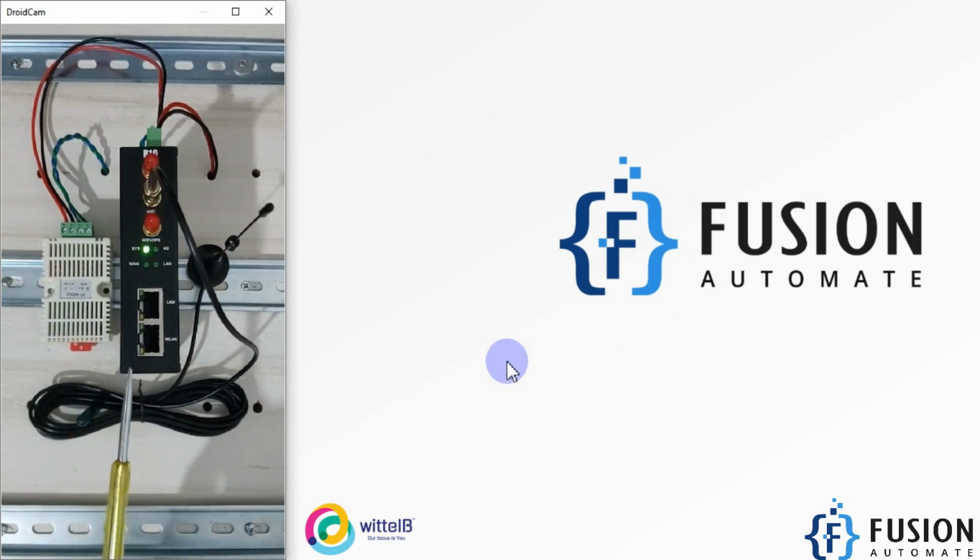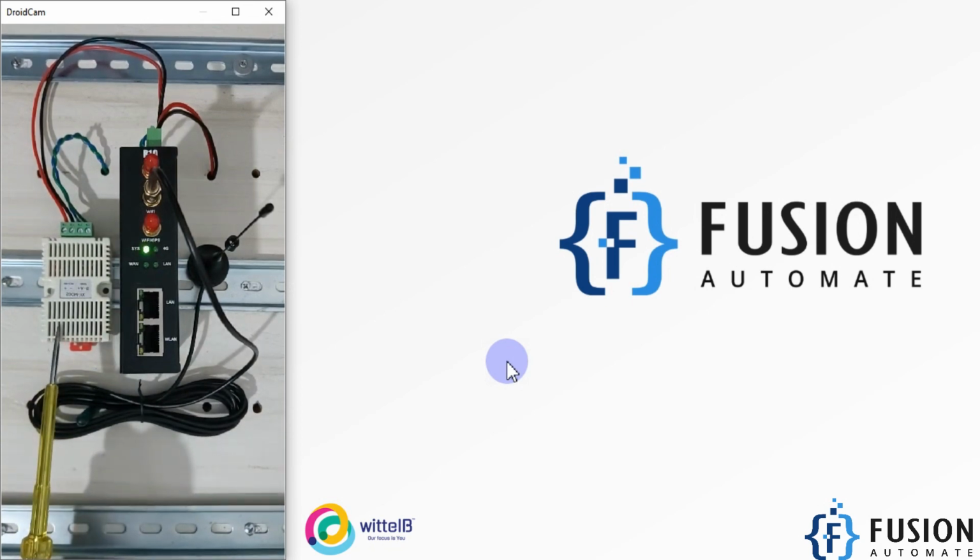This gateway is brought to you by Augmatic Technologies Private Limited and it is a very useful gateway. We have covered how we can use this gateway to convert our Modbus serial data into Modbus TCP data. Also, we have covered how we can use this gateway as a Modbus master and read the data from a Modbus slave device.